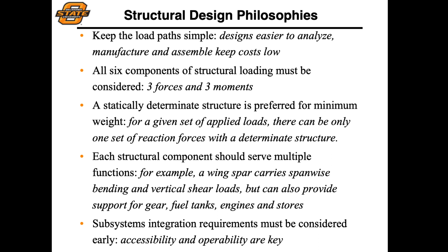Also, a statically determinate structure is going to be preferred over a statically indeterminate structure, and this will give you the minimum weight potential for that particular design. Thus, for a given set of loads, you really want to be able to determine that there's one set of reaction forces for that particular structure.